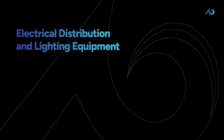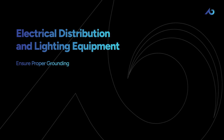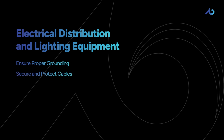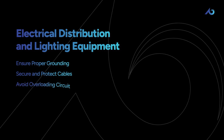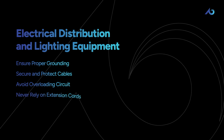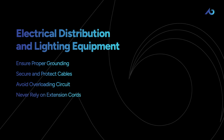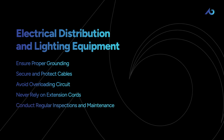To minimize these risks, ensure proper grounding of all electrical systems to prevent electrical shock. Secure and protect your cables from damage with industrial-grade conduits and cable protectors. Avoid overloading a single circuit with multiple devices or power strips. Never rely on extension cords for long-term use, as they could deteriorate over time. And conduct regular inspections and maintenance of electrical systems to identify and address issues early.